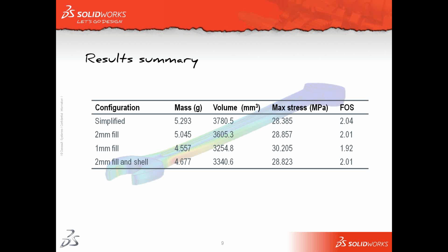We can see that the 2 millimeter fill and shell configuration is just above that 2 factor of safety that we need. And so being just over, we haven't got excessive amounts of structural material in there. So perhaps that's the most suitable one.